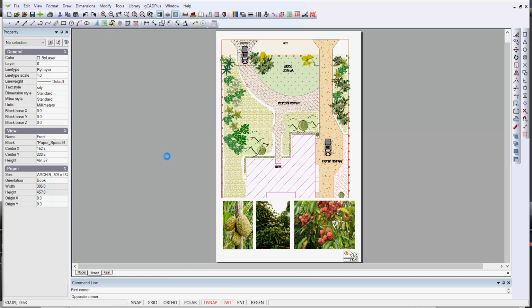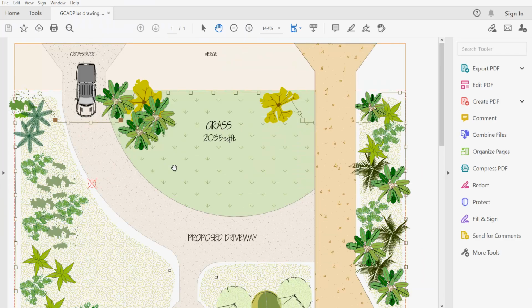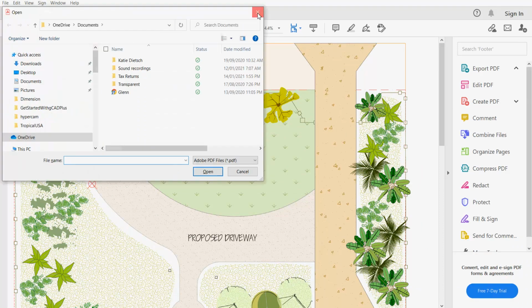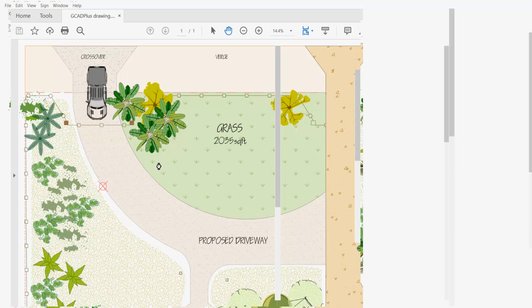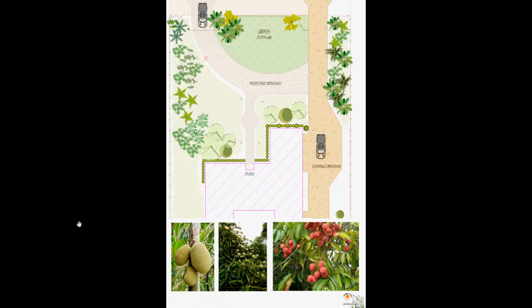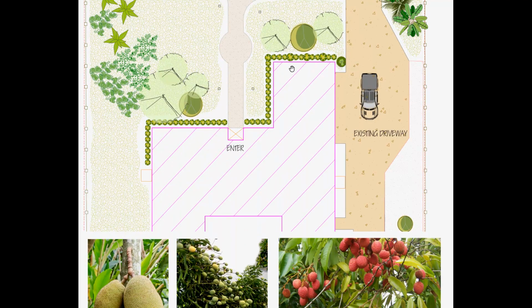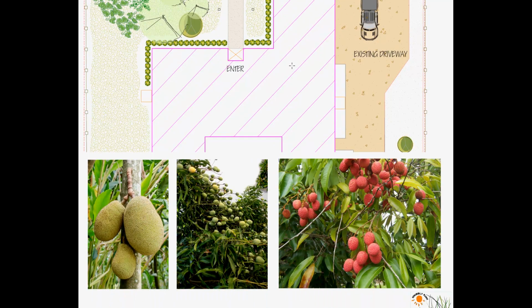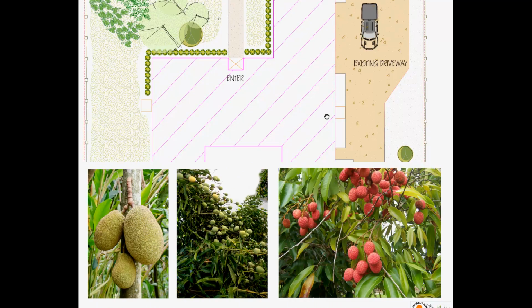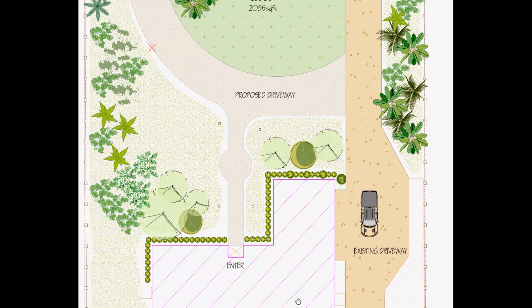So that'll give a very quick PDF file. It's an impression of what the client might see if we print to a proper driver. So let's go Control O, Control L is it? And that gives us the whole sheet. And if I use Control Plus, we can zoom in and then we can pan down. So you can see the symbols look good, and the images are at quite respectable resolution. You do much better than that, of course, when you go to a high resolution file.